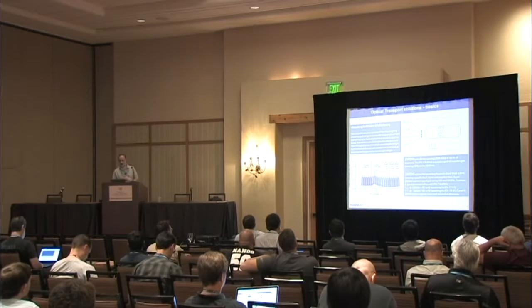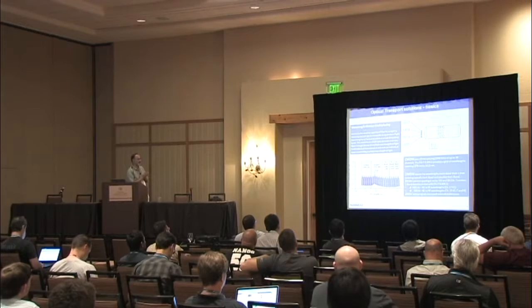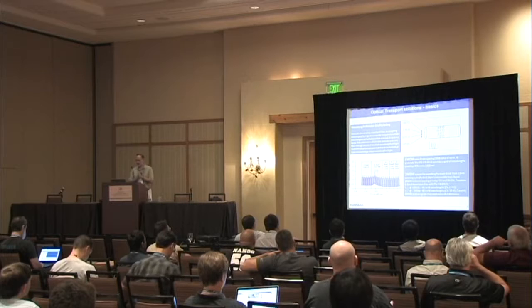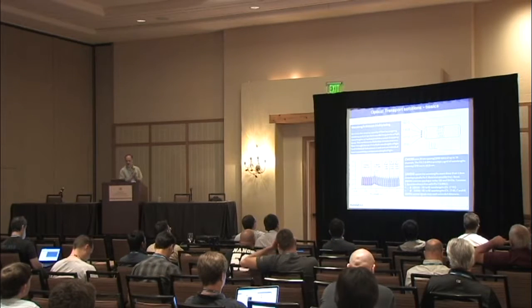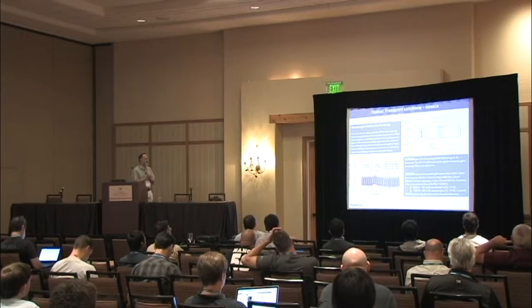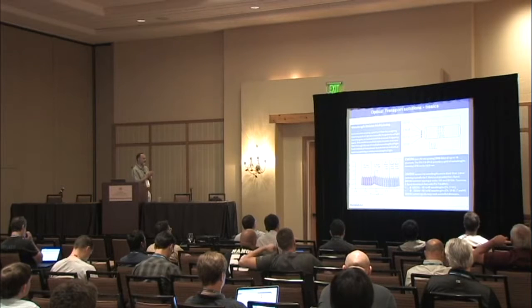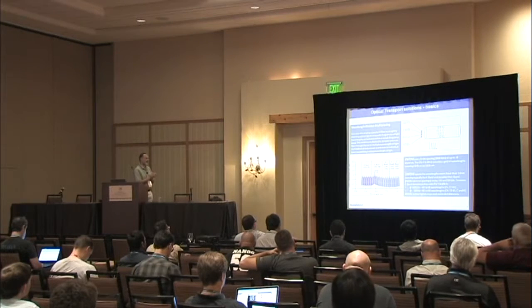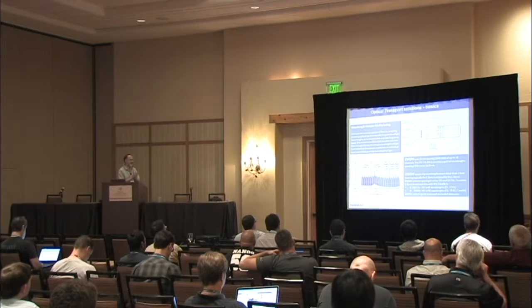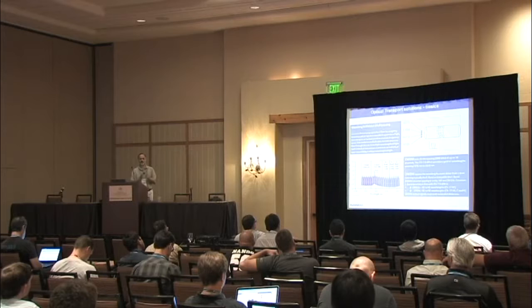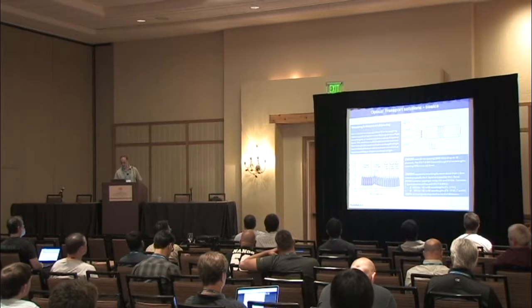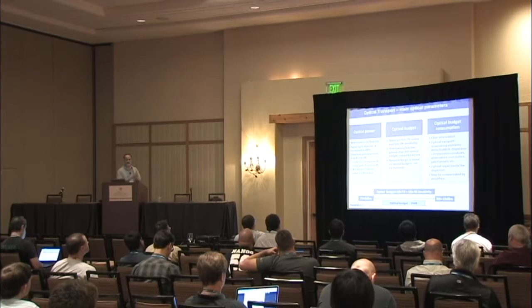You have in the industry two types of WDM, coarse wavelength division multiplexing using 20 nanometers spacing, and that defines per ITU standards 18 wavelengths in the range of 1270 to 1610. DWDM on the other side spaces more closely. I think the limit is 1.6 nanometer, covering typically the C band and possibly the L band. And you can get, depending on the spacing of 100 gigahertz, 40 to 48 wavelengths, channel 17 to 61, or 80 to 96 wavelengths, same 17 to 61, but now centered at half frequencies in the middle. And good for us, DWDM optical signals may reach extended distances through amplification and through impairments management, amplification and dispersion management.